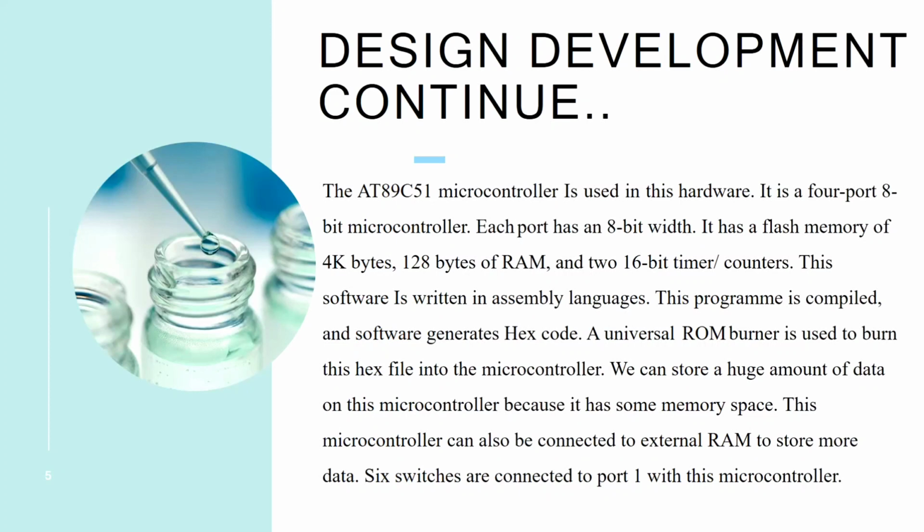The vote results were acquired using a hyperterminal in a computer connected to an 8051, and serial interrupts were used to do so. Any keystroke on the keyboard will cause an interrupt, and the results of the vote will be sent to the computer in order, starting with candidate 1 and ending with candidate 4.